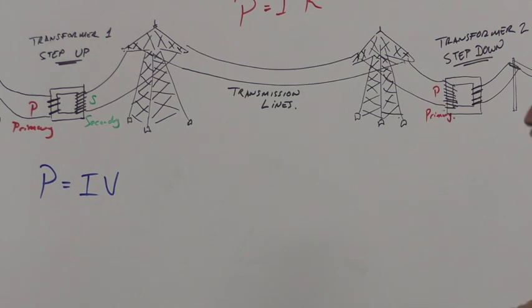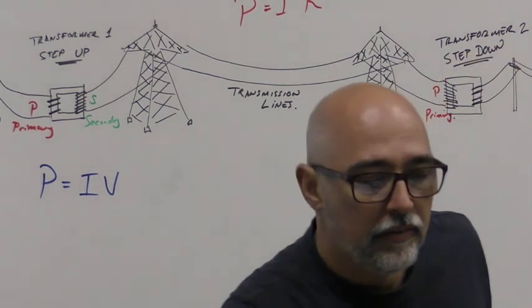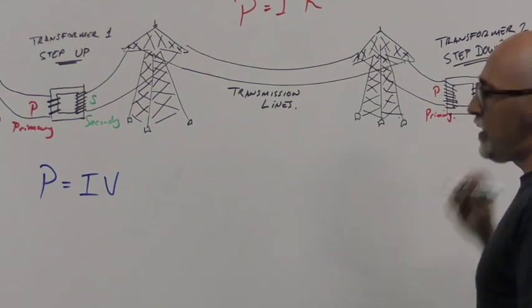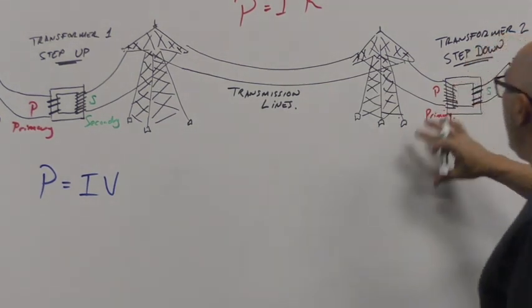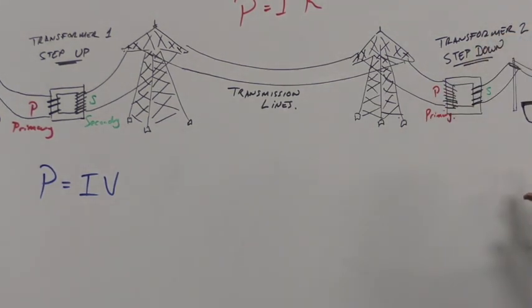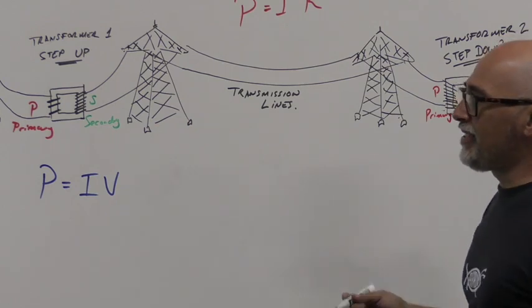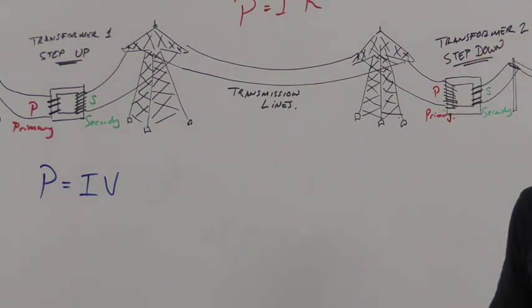It does its job of stepping the voltages back down again and the current back up by doing its thing and inducing a lower voltage in the secondary part of the transformer. So that's why this is now the secondary. Alright? Notice the transformers themselves are exactly the same thing, they're just flipped.